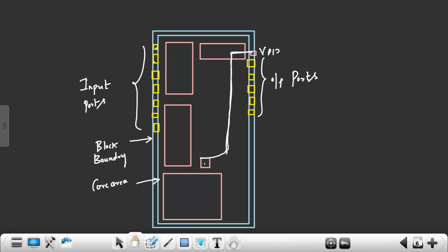Metal has internal resistance, which is a well-known thing. Current is flowing through this metal layer, and that leads to V equals I times R. Current is flowing and metal has internal resistance. So if my VDD is 1.5 volts, out of 1.5 volts, only 1.2 volts will reach the cell. The remaining 0.3 volts will drop on the metal layer itself, and this 0.3 volts will convert into heat.